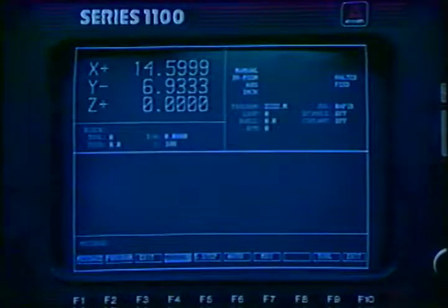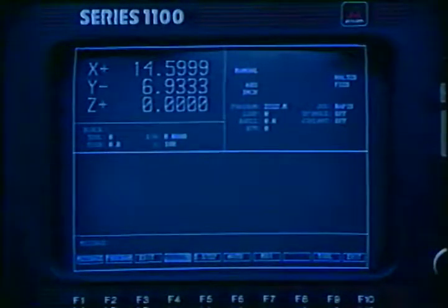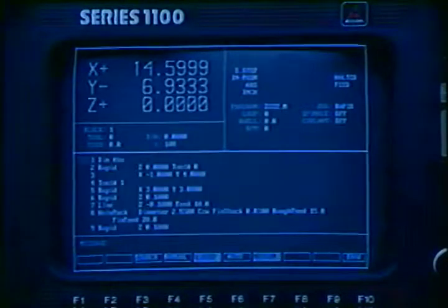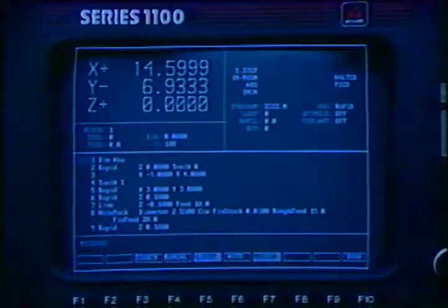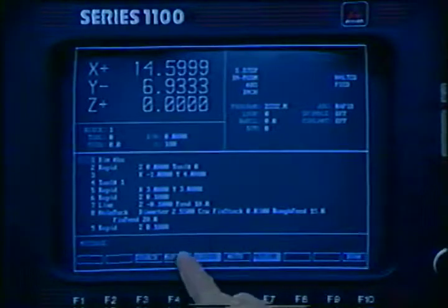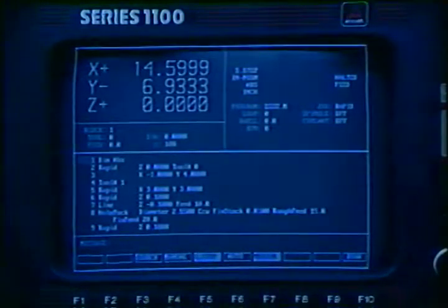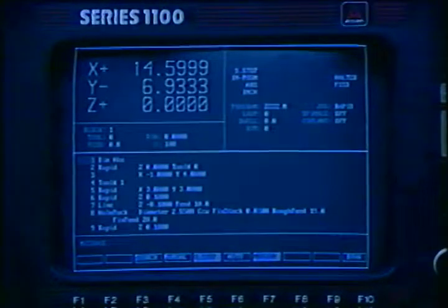The dark section below it will display the CNC program when you're in the single step or auto mode. To demonstrate, I'll power up the servos, go into single step mode, and you'll see the program appear here. As the program is executing, the blocks will scroll up the screen. Just below that section is the message line. Especially in 2-axis, you will get messages to position the Z-axis and press start, or prepare for a tool change